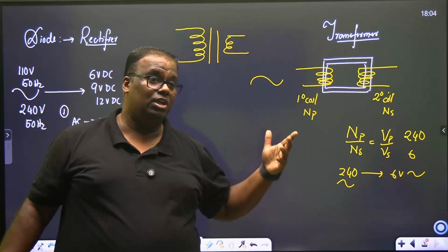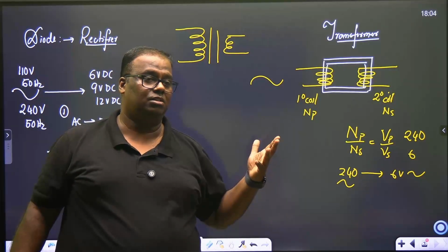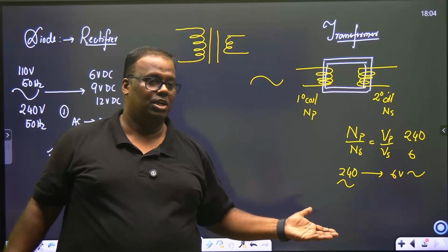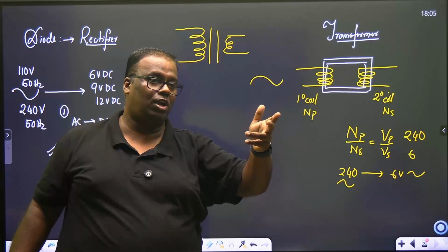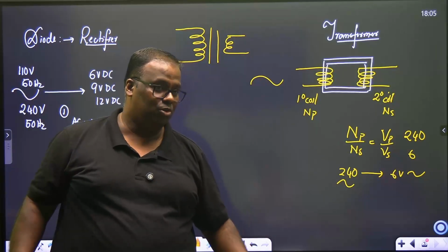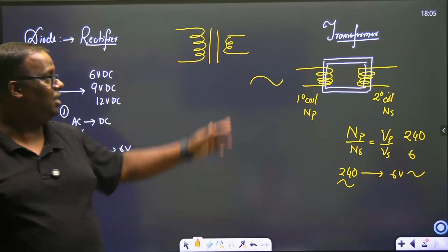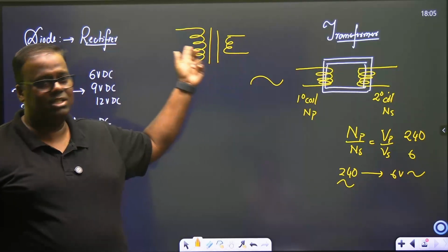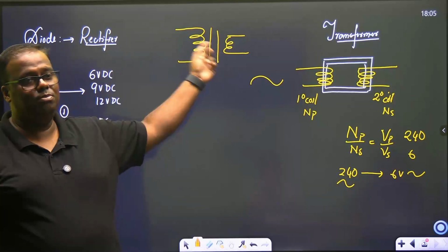There the voltage coming in is 13 kV, 13,000 volts. At home you are using how much? 240 volts. 13 kV will be dropped down to 440, and at the basement of the tower, 440 gets converted to 240, because you need less voltage. Right? And you can do the reverse also. The reverse is called a step up. Lower voltage can be stepped up to higher voltage.